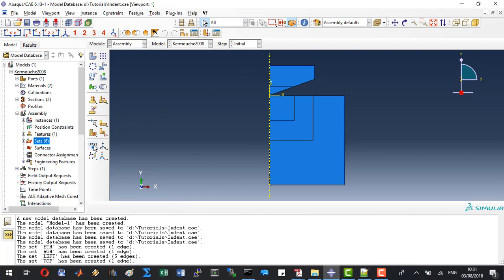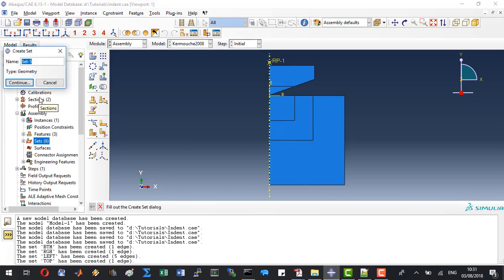click OK, and here we have to create a reference point which is going to be measured from this point. We will add 1 times 10 to the power of minus 3 equals reference point. And creating the reference point, we will use this reference point to actually measure the reaction forces which are on the indenter.